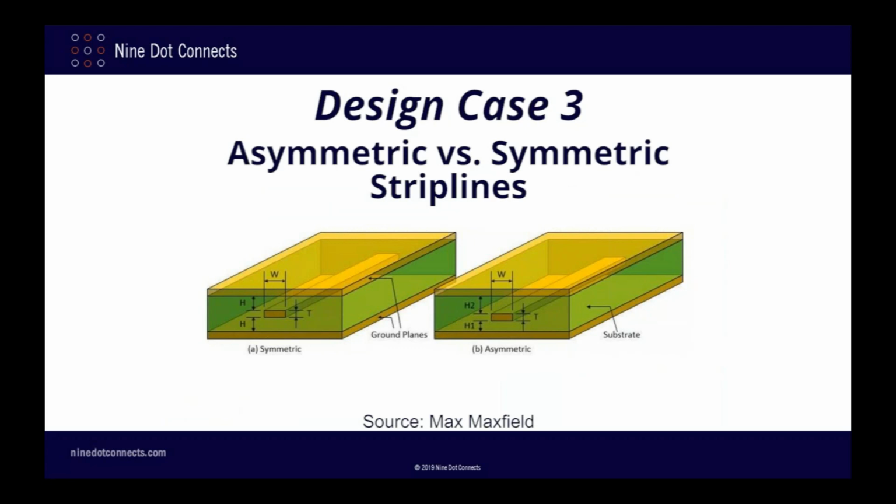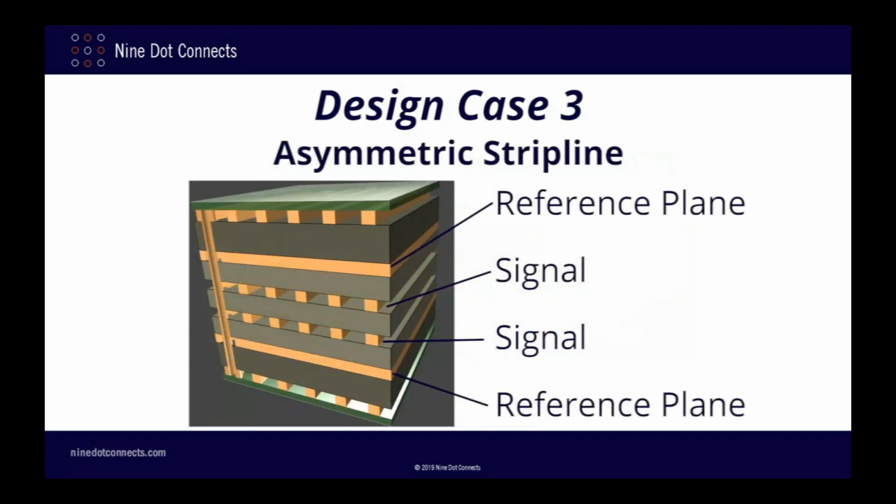Except in cases where the signal integrity is absolutely essential, you will rarely use a symmetric strip-line stackup. More often than not, you will actually be using a variation of the asymmetric strip line. From a stackup and routing perspective, this means that you will have a reference plane, 2 signal layers, and then another reference plane. You may ask, why would this be considered strip line if there is another signal layer on one side of the trace? In fact, the dielectric thicknesses and trace dimensions are calculated as if the other signals are not present. Thus, we really have 2 overlapping asymmetric strip line stackups.